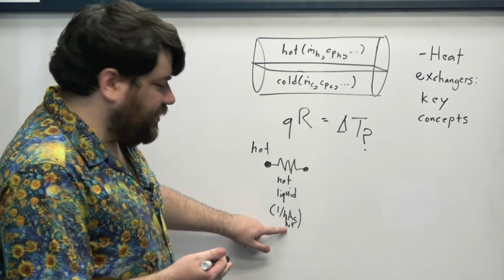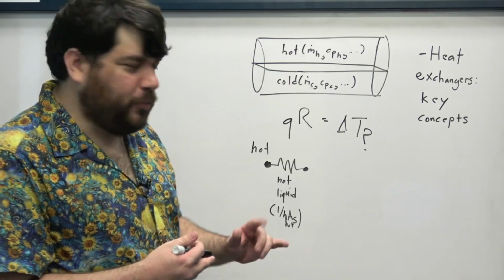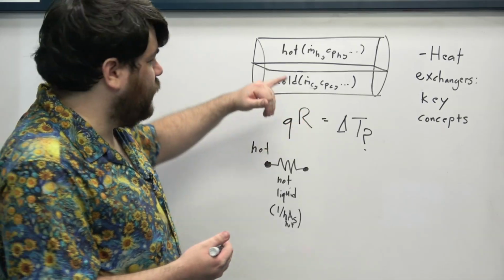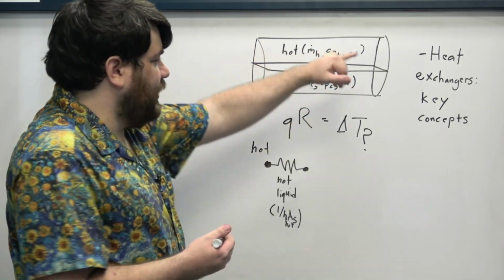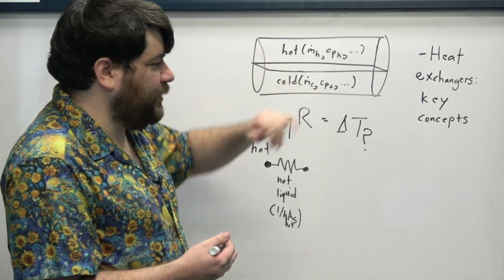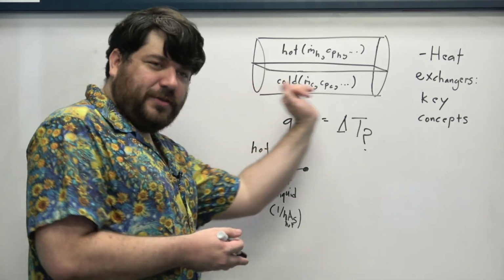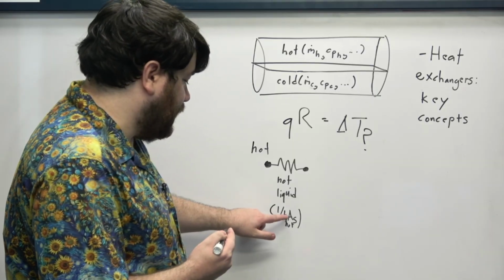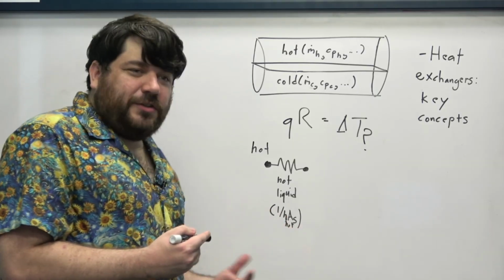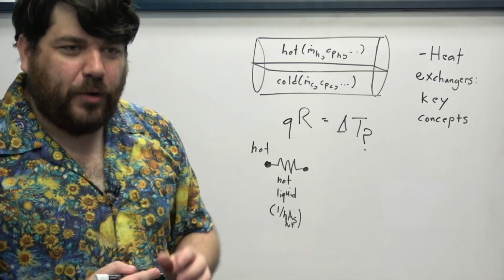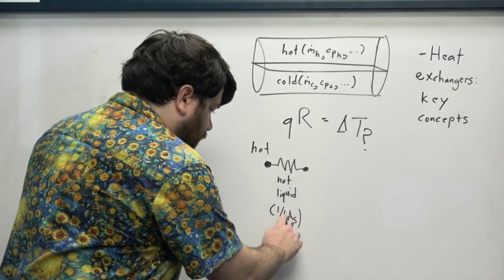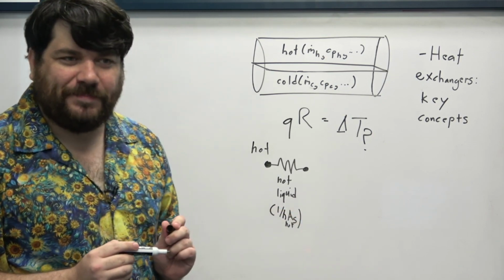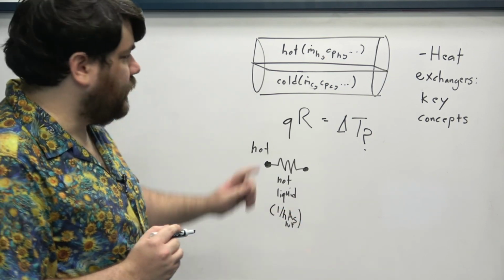Now I put the subscript hot down here because the whole point is that the heat transfer coefficient between the hot liquid and the plate is not necessarily the same as the heat transfer coefficient between the cold liquid and the plate, okay? So we have to be very careful about that. But the convective resistance is nevertheless written in the exact same way. All right, so sorry if this looks a little bit bungled, but hopefully this is a bit more readable. Okay, so we have this.